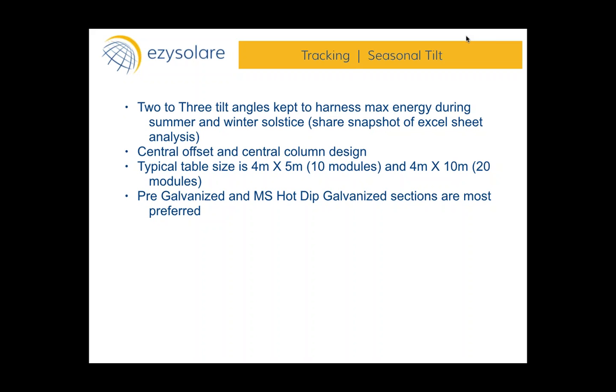So it is centrally supported. The moment you unlock the bracing for tilting it, the structure's tendency is to come to 0 degree, or otherwise on very little effort it can be brought to 0 degree, and the bracings can be realigned to the slotted holes or whatever your tilting mechanism is. So we strongly recommend going with a centrally supported column rather than an offset column, and a two bracing model and not a one bracing model.